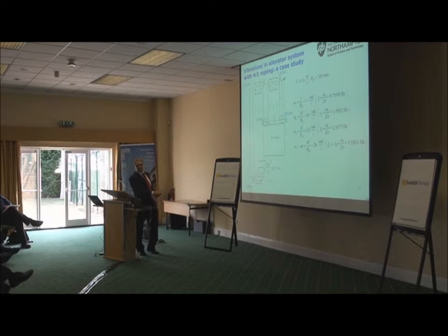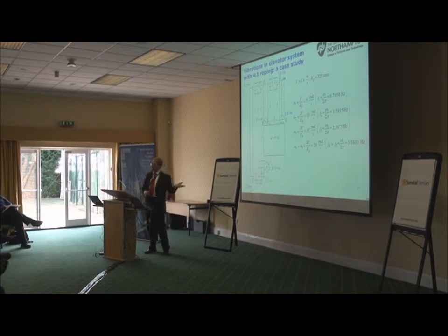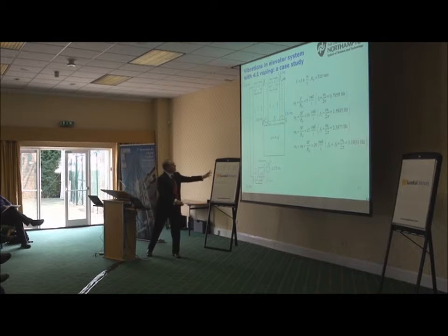Okay, what we have is a heavy car suspended on a suspension rope which goes through a number of pulleys, 4-2-1. 4-2-1 is prone to have a lot of pulleys, and when they have a problem with the pulleys, they cause vibration. So what we do first, we need to identify some key parameters of such a lift system. This will typically be the velocity of the car and the diameters of the pulleys. And when we have this, we can calculate the frequencies which correspond to rotation of the pulleys. 1, 2, 3, 4, 5. Here's a set of 2, set of 2, set of 2.